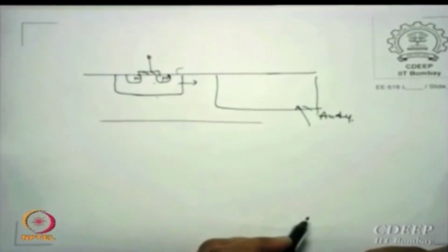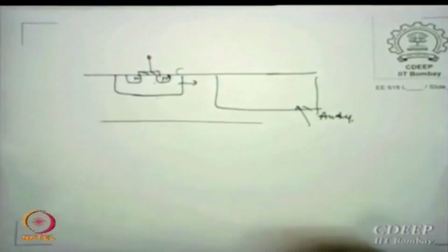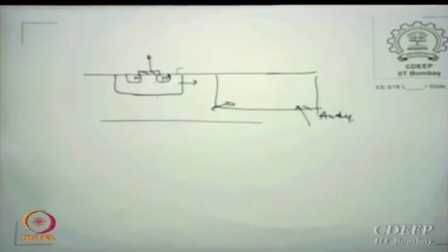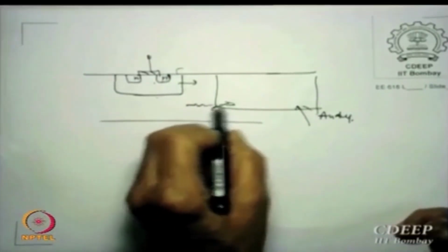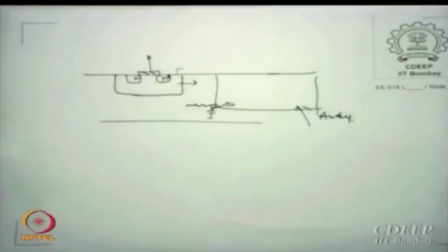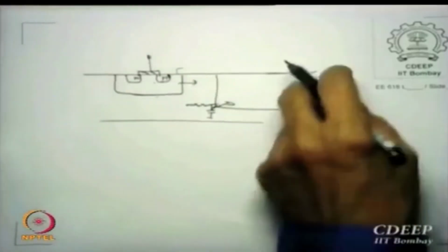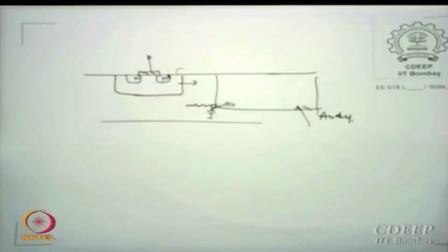When you switch 1 0 1 0, the substrate also gets 1s and 0s, but this analog area is sitting on the same substrate, which may have the equivalent of resistance, sometimes capacitance. So this change is getting transferred to analog irrespective of whether you want it or not. This is called substrate noise coupling.